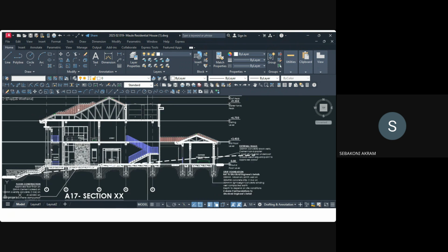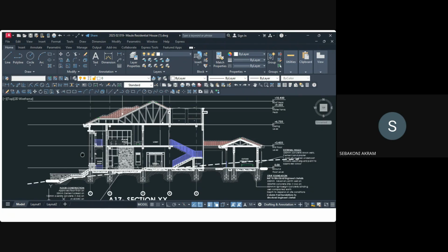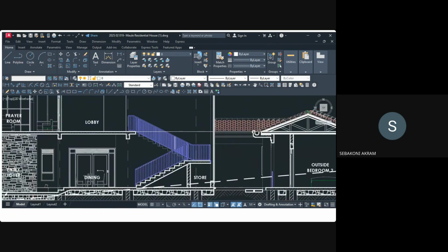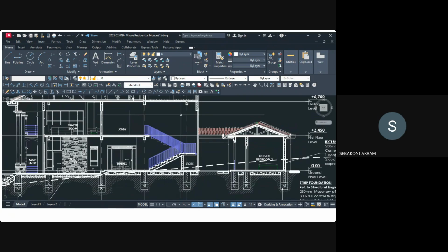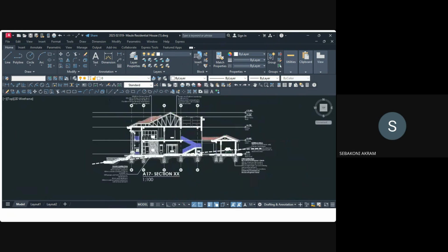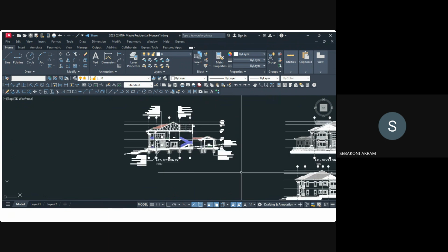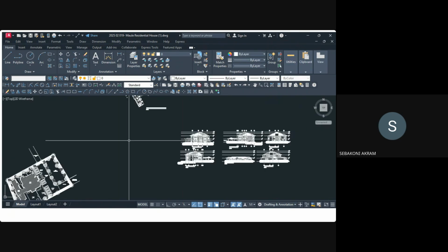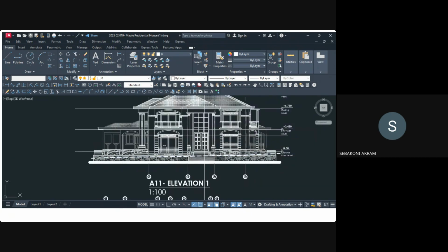So, as I was telling you, before cleaning, this section is an important bit of a drawing to understand. As you're designing, you'll have to refer to it, because you see this staircase. As we're going to see in other sessions of the learning process, you would see how we would place the lighting, how this section is important in that way. For the meantime, because we don't design from it, we design from floor plans, we're going to delete also this one. You select and delete. So we do have our elevations.